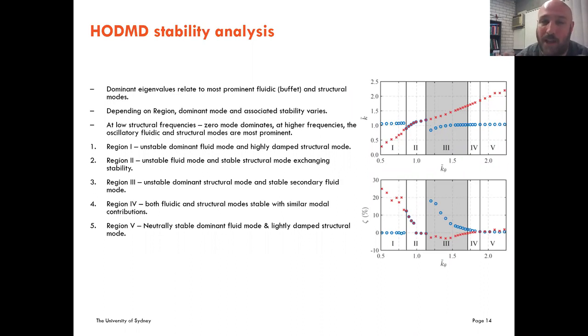The higher order is where you repeat the response with a time delay. You're still linearizing the system, getting a localized snapshot of the frequency and damping of your data. But from that, you can make a distinction between the structural mode and the fluid modes.